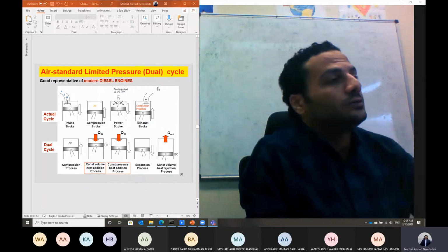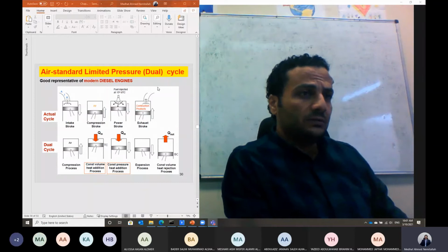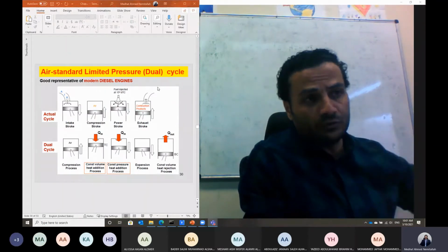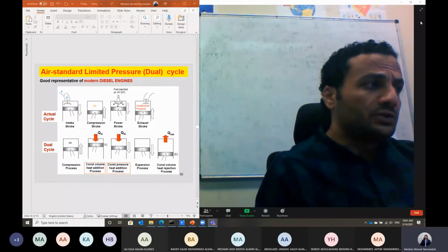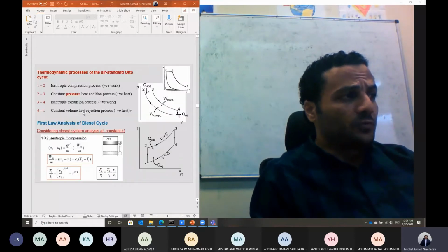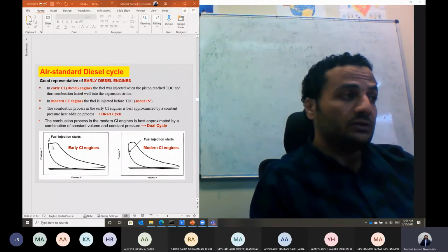Let's continue our talk today. We talked last time about, we finished our talk about the diesel cycle. We have represented the cycle that can be applied for the early version of the diesel engine, in which, as we said, the injection just occurs at the top dead center, and all the combustion process just takes place during the expansion stroke. This is the early version of the compression ignition engine.